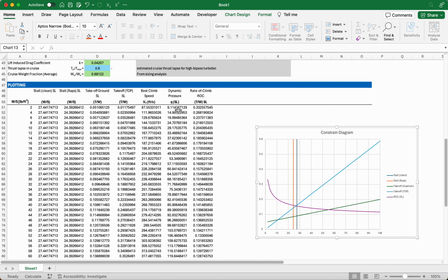So if you set your rate of climb to 100, then you have the requirement for your service ceiling by then solving what that density would be at whatever altitude given a thrust to weight ratio. That would usually come in more so with performance, unless you have a service ceiling requirement for your aircraft. This aircraft has a pretty high rate of climb requirement.